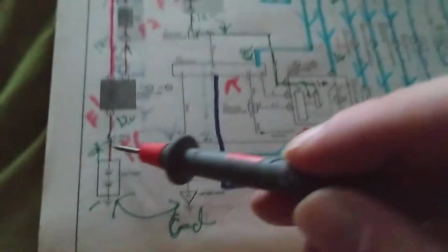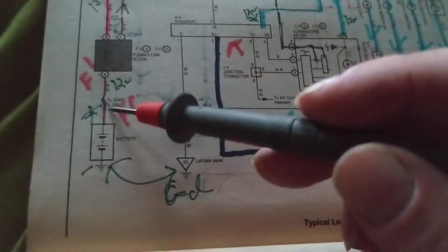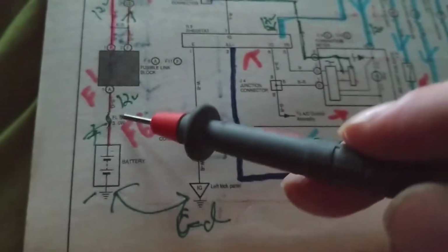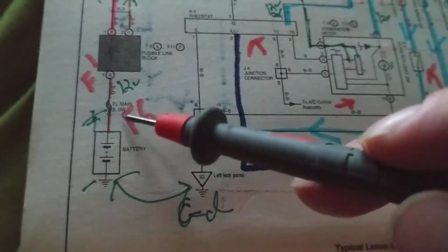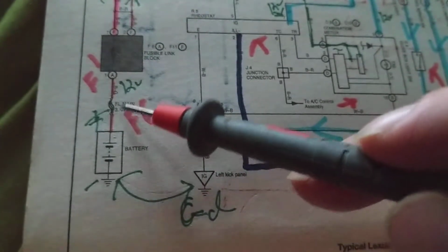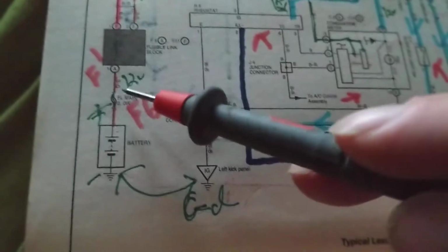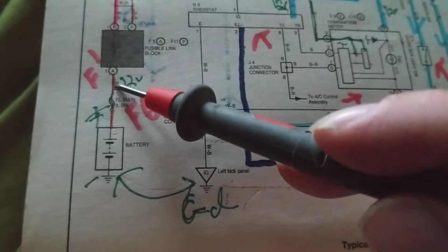So, keeping that in mind, I want to measure the total current going through this. Where would I put it? There are one or two ways to do it. You have to break the circuit. You could take this fusible link out, put the meter on amps and measure in here. Where would the positive of the meter go? Right here. The positive goes here, the negative goes here.